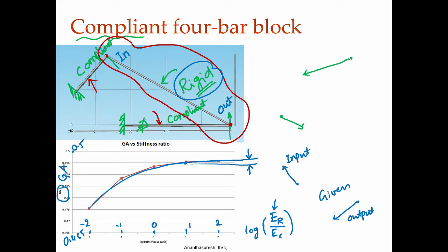So, 10 times is really easy, just make it, if you have some in-plane width for what is supposed to be a compliant segment, you make it twice as wide. Okay, that is the depth of the beam. Let us say this is D, you make it 2D. When you think about second moment of area, that is BD cube by 12, if it is 2D already becomes 8D cube, whereas here it will be just D cube. So, we get 8 times.